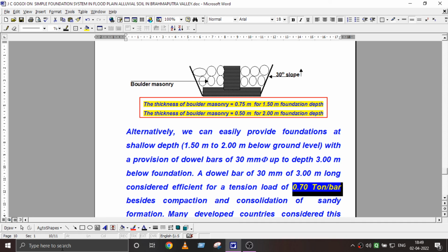I personally saw that 3 meter, 4 meter bamboo piles were installed within a day. A bigger foundation, about 9 meter by 9 meter, 8 meter by 8 meter, with bamboo piles and sand piles, they complete one foundation a day. So it is very effective.